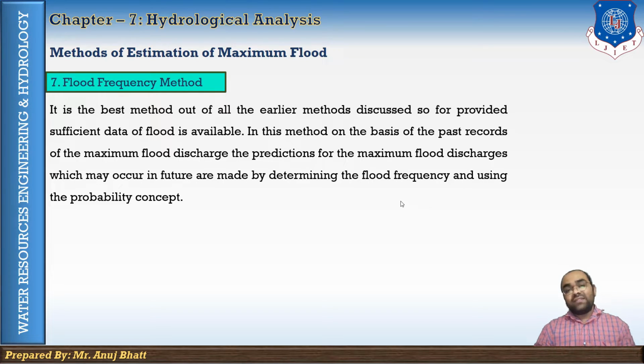Frequency analysis makes use of the observed data in the past to predict the future, based on some assumptions that the combination of the numerous factors which produce floods are a matter of pure chance and therefore are subjected to analysis according to the mathematical theory of probability.